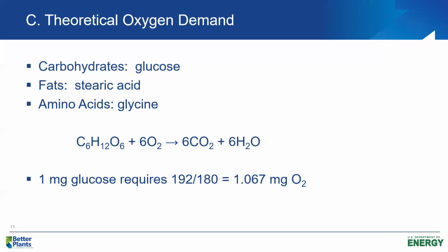But what I was able to do in the case of this East Tennessee treatment plant was determine the ultimate BOD of whiskey, and then I had made some estimates about the BOD5 to ultimate BOD ratio, and I came up with an approximate value of the BOD5 of 100 proof whiskey in the neighborhood of about 650,000 milligrams per liter.